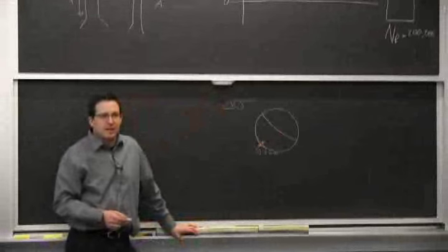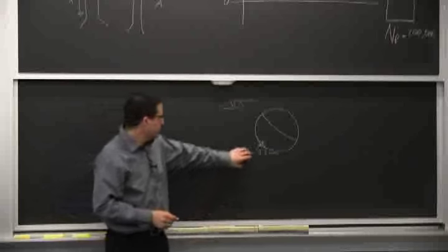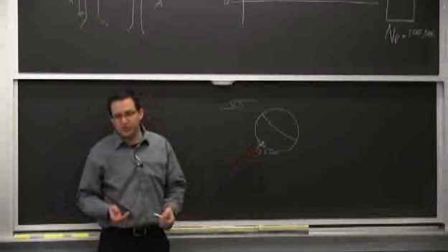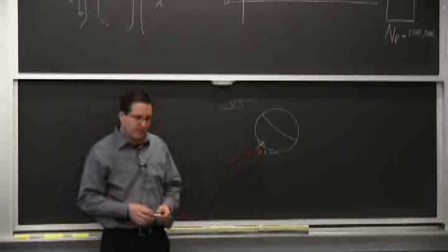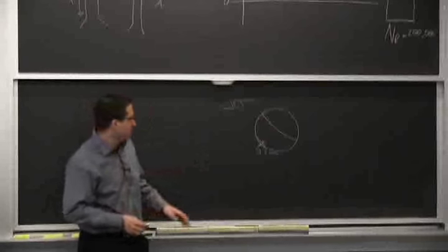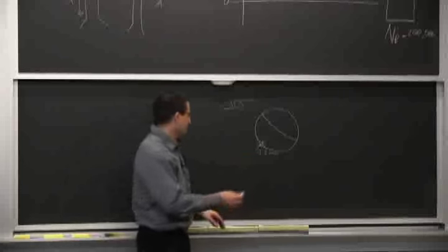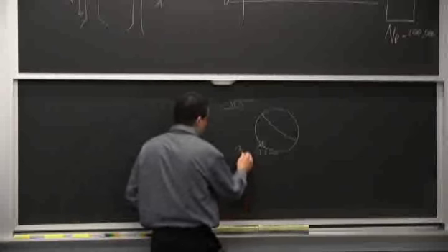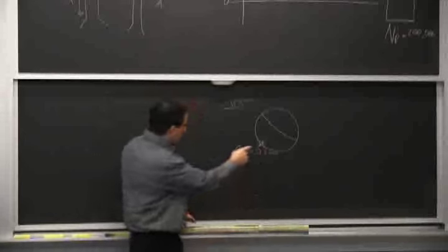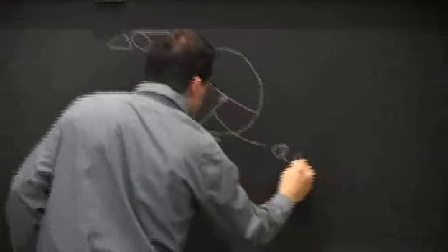And that is, as you can probably imagine, more conservative because it's assuming a problem to begin with. It's also called a damage tolerant approach. That's the general keyword in the aircraft industry to speak to having a defect to begin with. And I'm putting this size here, so that would be AI when we get to the equations later. Initial size of the flaw. And then we have AF, that's the depth of the crack when we reach an overload factor.